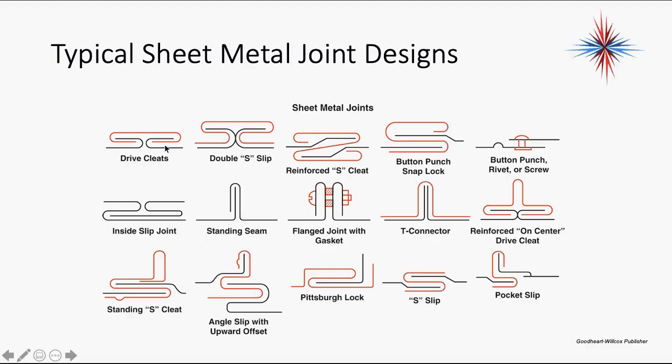When you install sheet metal ductwork, wherever there's a joint, we paint it with a sealer called mastic. It's a heavy sort of cross between paint and plaster of Paris, I think is my best description. You paint it on there and basically seal the ductwork.